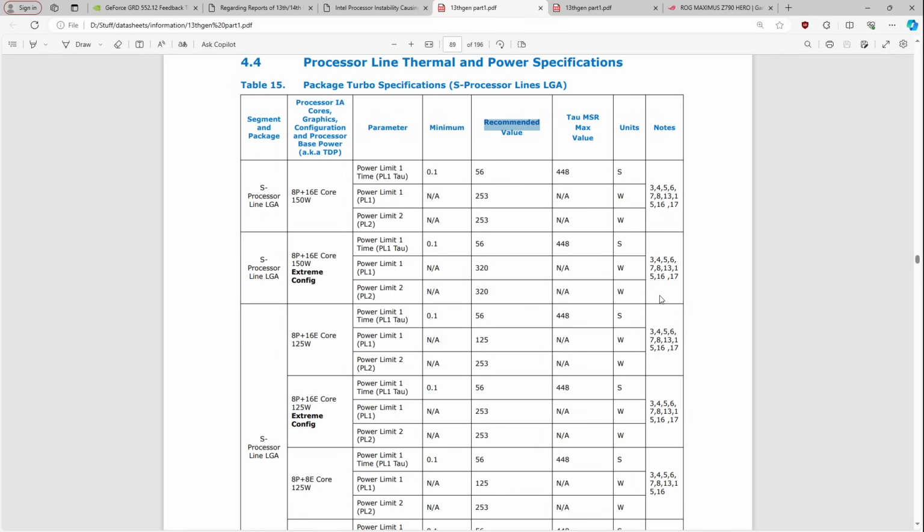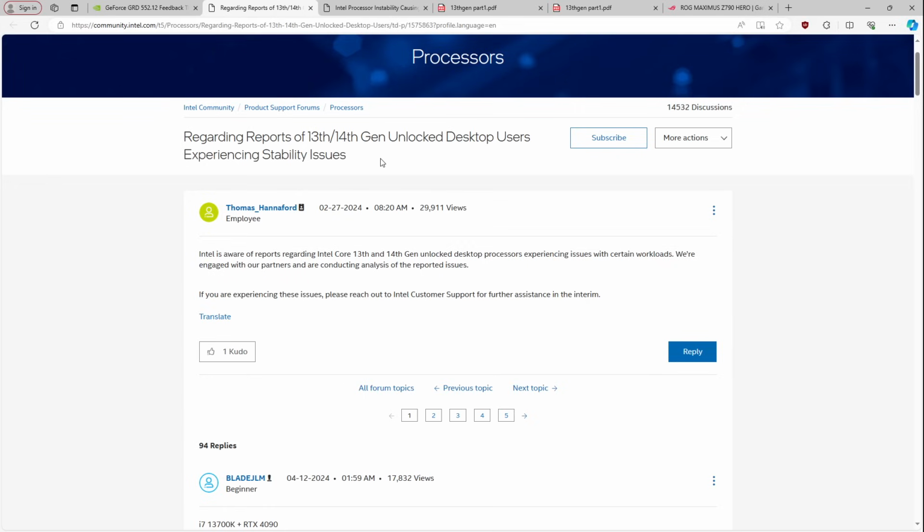And the reason I find the rumors of 13th gen, 14th gen CPUs degrading on out-of-box settings hard to believe is that testing for degradation is really quite hard and tedious, because you need to first validate some settings. You would need to have: this CPU can definitely run X frequency at Y voltage for some really long endurance test, so I don't know, 24 hours of say 5 gigahertz at some voltage. And then maybe 6 months later, you would run that test again at that same voltage, and that voltage has to be really quite minimized.